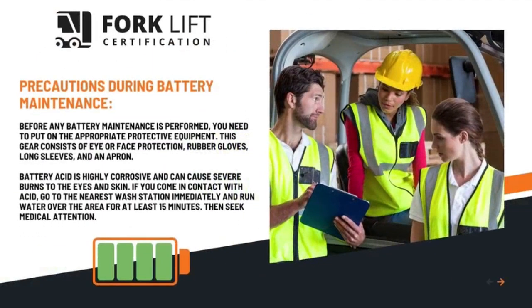Precautions during battery maintenance. Before any battery maintenance is performed, you need to put on the appropriate protective equipment. This gear consists of eye or face protection, rubber gloves, long sleeves, and an apron. Battery acid is highly corrosive and can cause severe burns to the eyes and skin. If you come in contact with acid, go to the nearest wash station immediately and run water over the area for at least 15 minutes.